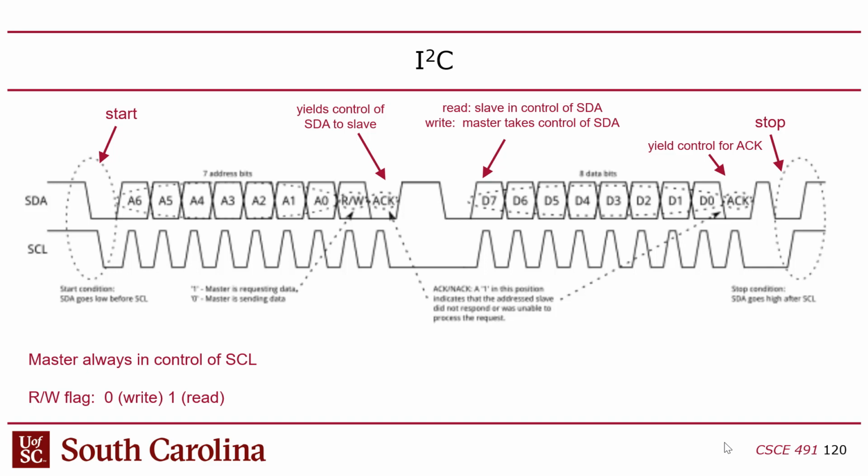Okay, so the idea is that whenever that clock is high, that's when you send data through. And then when you lower the clock, that locks in the data, and that's also when the data is supposed to change. So the data changes when the clock is low. It's supposed to remain stable when the clock is high. So when the clock is high, it's like you open a gate, right? You can get data through when the clock is high. When the clock is low, you close the gate. That allows you to change the data, so the next time you open the gate, the new bit goes through, right? So what that means is that the data should never change when the clock is high.